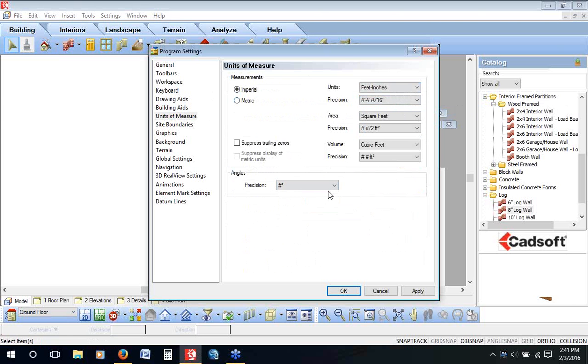But knowing that if I type in now 12.5 degrees, it's going to truncate off the 0.5 degrees. It'll be just 12. And I won't see the 0.5 because I've told it that I only want to work to a precision of full degrees. If I come back later and change this to maybe hundredths or thousandths, it will then say that that is 12.5 degrees. It knows it's 12.5, it's holding that, but it's truncating that off in any values that it's going to show you because you've told it you only want to work to full angles.